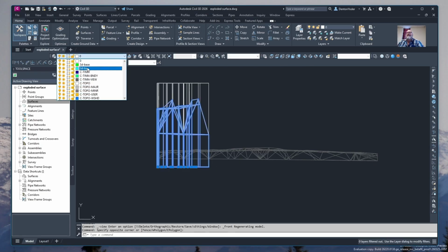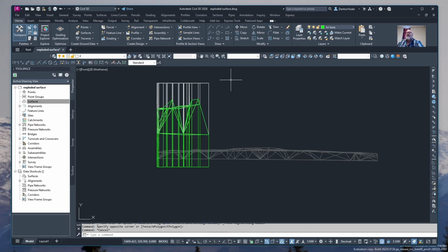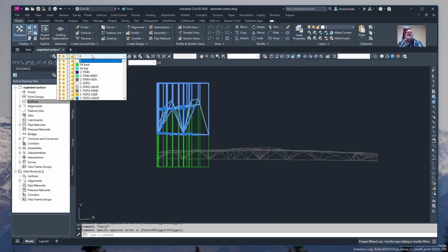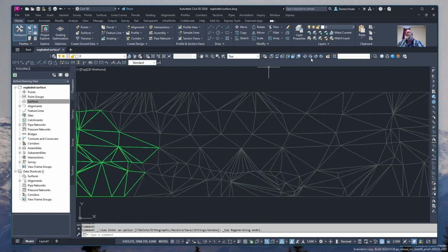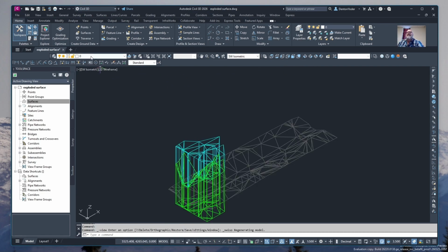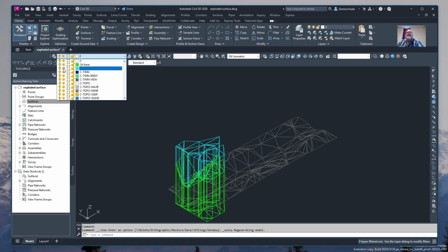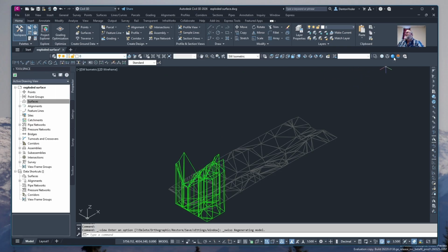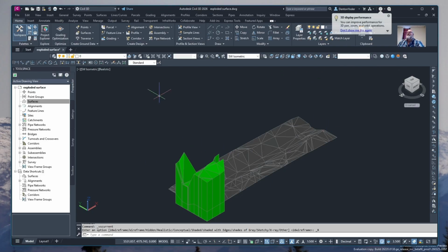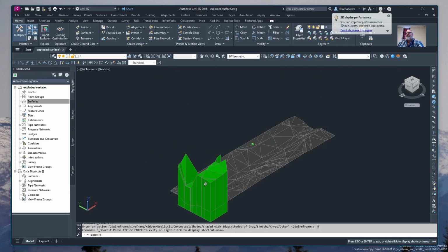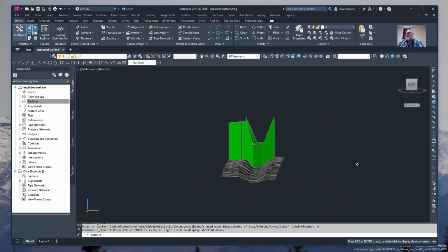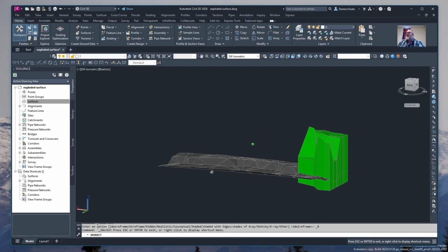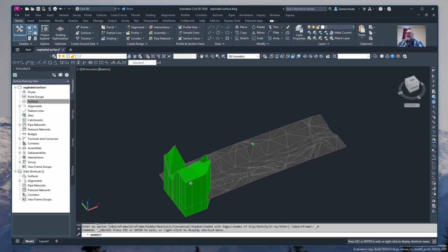These are going to be the base, and this is going to be the top. So everything, I'm going to go to top view, then an isometric, freeze my top, turn on shading, and you can see a lot more exaggeration. Instead of a small exaggeration, you have a huge exaggeration, and that was a 4 times vertical exaggeration.